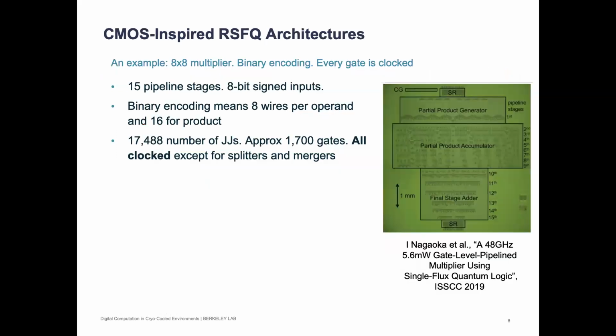So scaling up. A lot of the work that has gone into this superconducting technology, and by the way, the logic family that I'm talking about here is what's predominantly used today, not the only one, and that's called RSFQ, Rapid Single Flux Quantum Technology. And a lot of the implementations that we've seen are what I call here CMOS inspired, which is really, let's take the architectures that we implement in CMOS, sort of copy paste, because the gates are the same, and so on. We can put them in RSFQ, and they work.